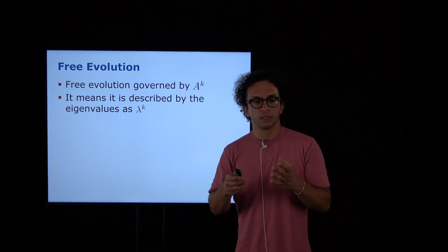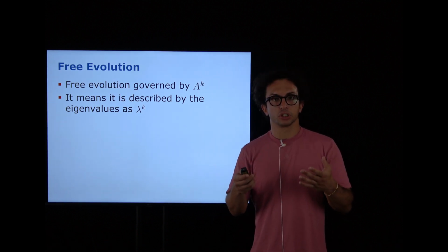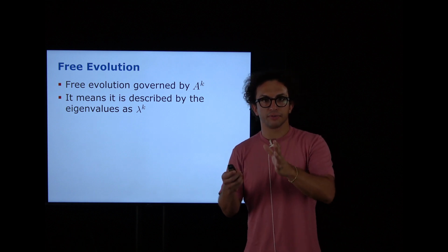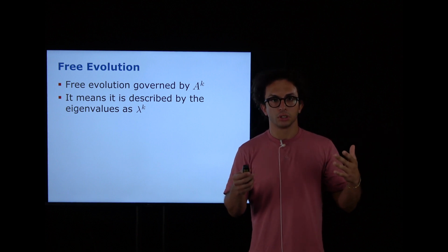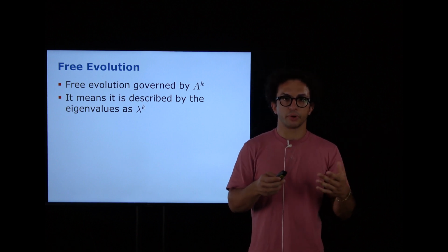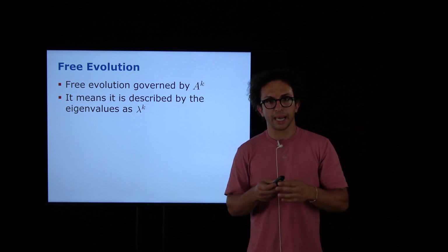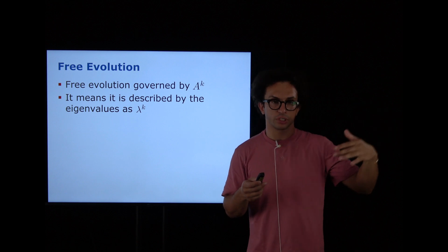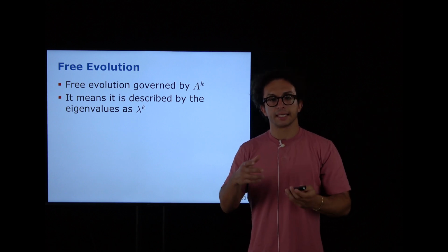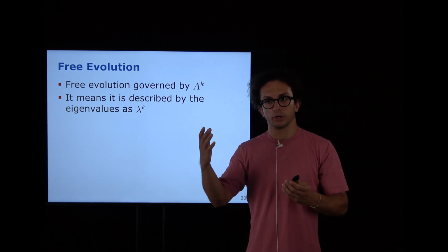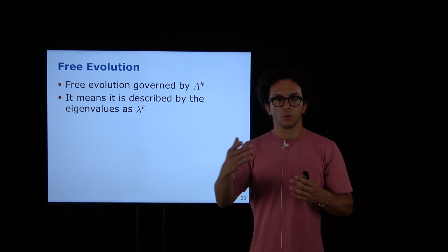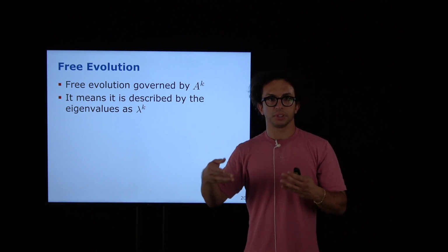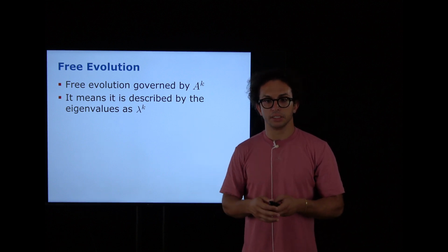And so, exactly like the exponential function works, the left half plane was something good, basically the stable part, because the evolution was decaying, since it was less than 1, something decaying to 0. And when the eigenvalues were bigger than 0, so on the right half plane, we had something diverging, something that led to instability.